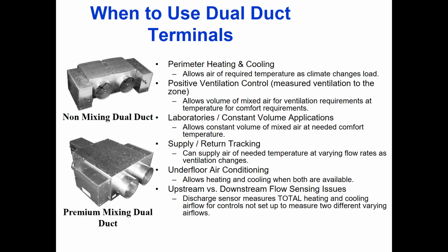Or you might see it on a new install in a real specialty application like a laboratory, but instead of hot duct and cold duct, you'll have a ventilation duct and a cold duct. And that way they can have dedicated ventilation air coming to that zone. So you might see them used in that kind of application for niche laboratory type spaces. But most of the time you'll see them will be on existing systems, and they'll have two different ducts coming to them and we're mixing it.